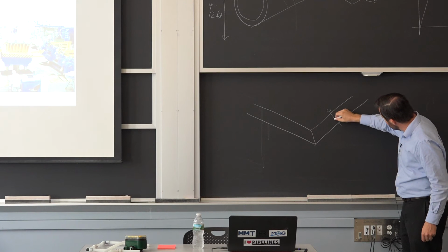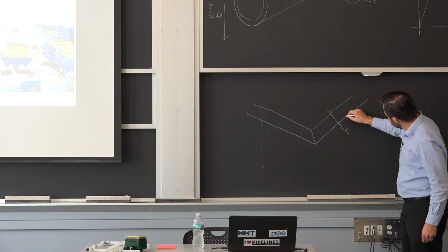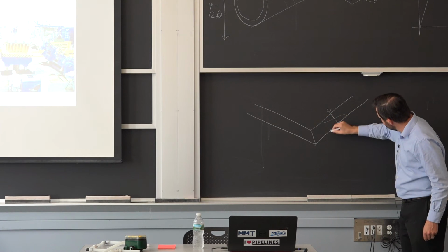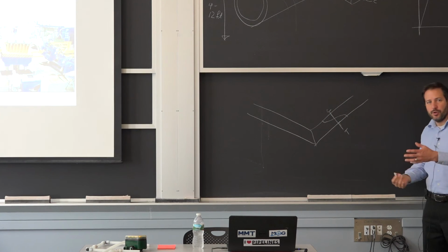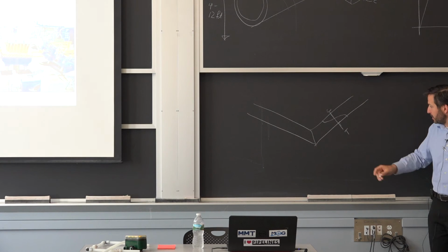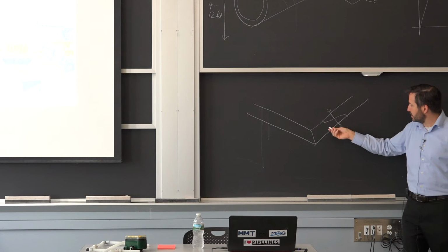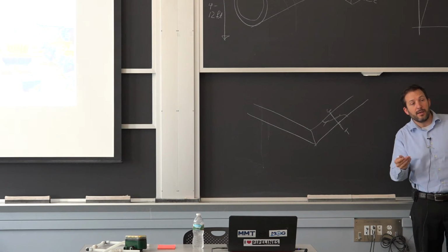If I'm looking at my stress profile right here, let's say this side is tension. It's going to look somewhere like this because it's yielding on each side. That's the loaded configuration, and when you unload it, it doesn't go to zero because you've deformed that shape. It's in maximum tension, maximum compression, and it's non-linear. In the center, it stays elastic.